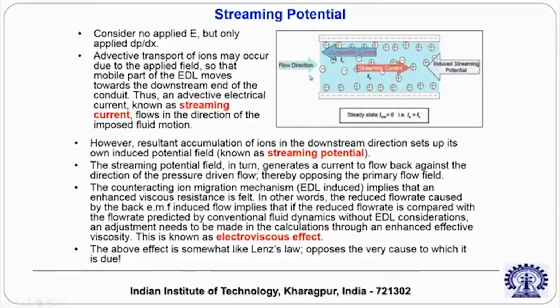So, here in electroosmosis the input is axial potential and output is flow. In streaming potential the input is a flow due to pressure gradient and output is a potential, and you can tap that potential to harness power, and we will discuss later on in one of our lectures in microfluidics for healthcare how this can be used to energize point of care diagnostic devices.